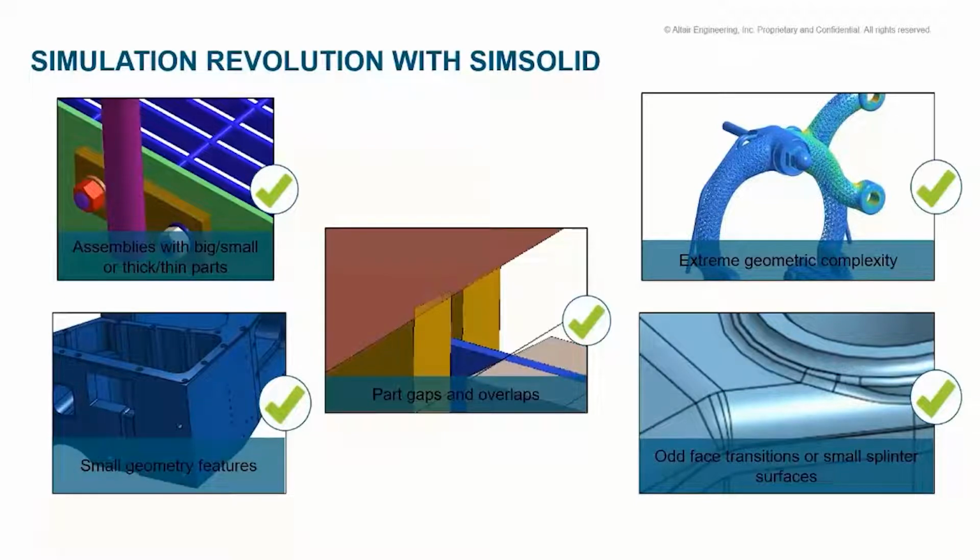You're not just limited to looking at the one type of results. You may have small geometry features inside your CAD itself, and you can keep all of these different small geometry features like pinholes or small fillet radius. You can keep them all in. You don't need to take them out because they don't cause singularities in your results.